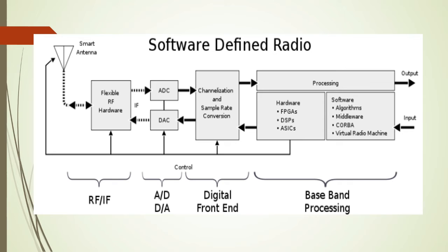The digital down converter is the counterpart component to the digital up converter, and it is equally important in communication systems. Its function is to translate a passband signal comprising one or more radio or intermediate frequency carriers to one or more baseband channels for demodulation.